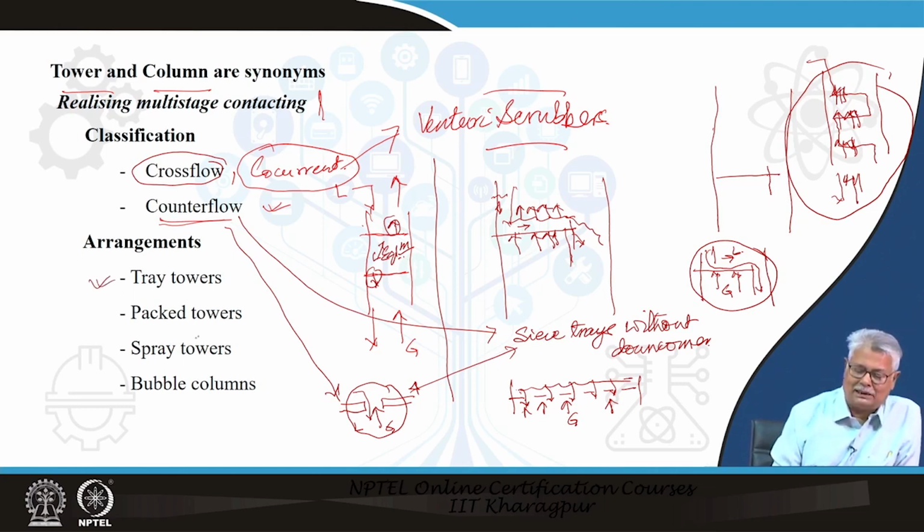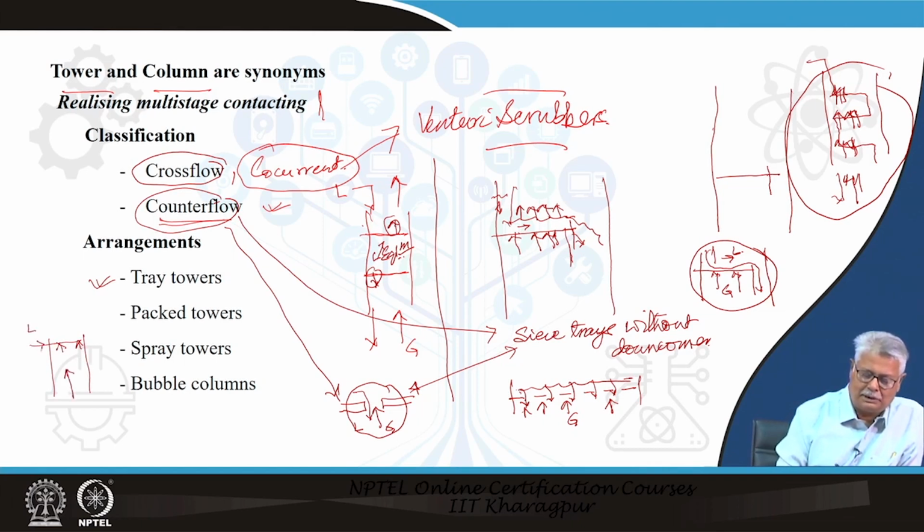We think about the pack tower, which we also have said specifically will definitely be the typical counter flow arrangement. And if we look at the other ways of conducting, I can also have a spray tower. I could have my liquids being sprayed inside a tower. My liquid comes in, it gets sprayed, and I have my gas counter currently flowing in that particular tower, and it becomes a spray tower.